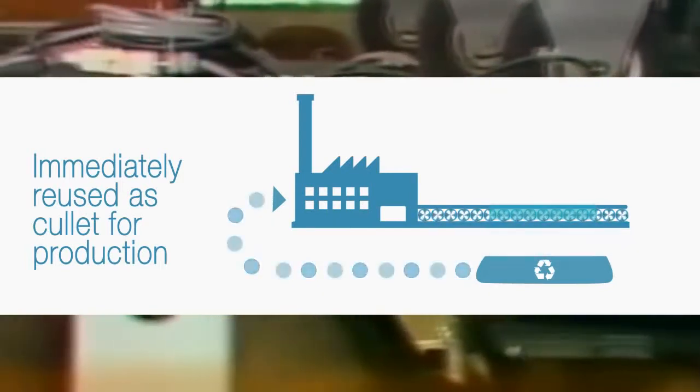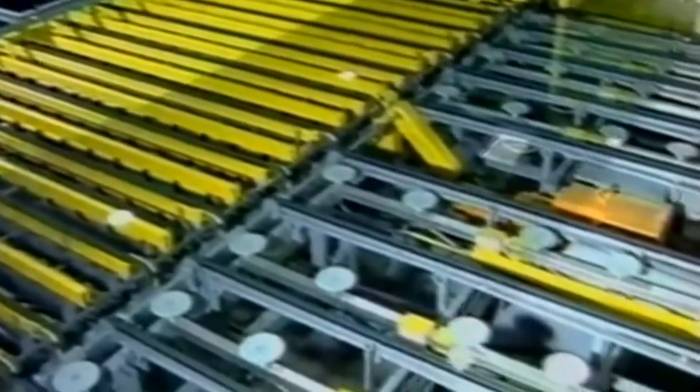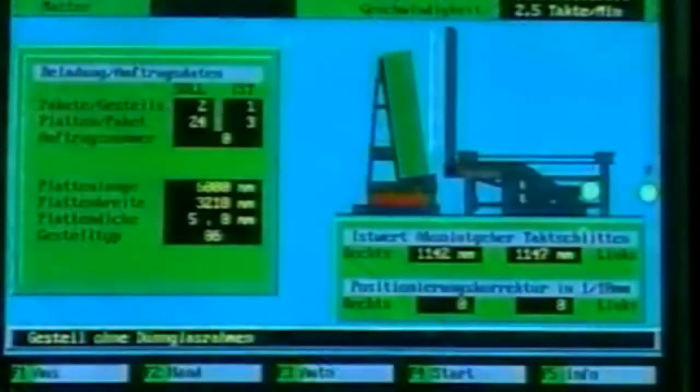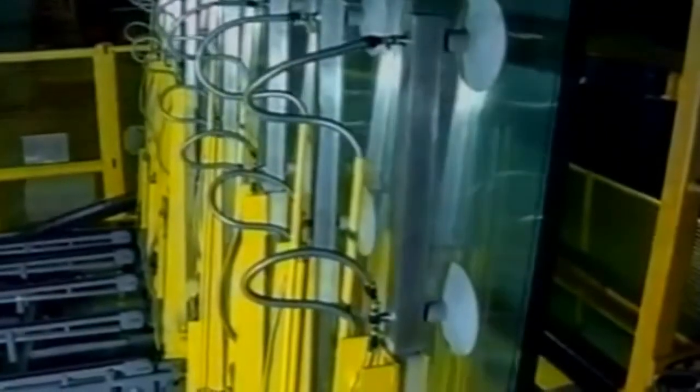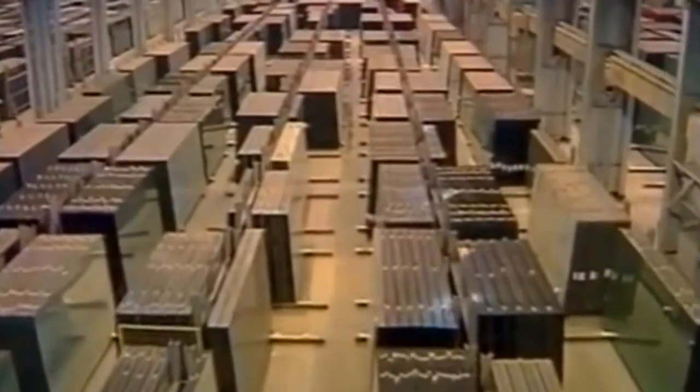The glass ribbon is cut either based on customers' orders or in standard industrial sizes. The most common size in industry is called jumbo. A jumbo piece of glass can weigh between 200 and 500 kilograms depending on the glass thickness. These final glass sheets have perfectly smooth surfaces. They need no further grinding nor polishing. They are ready to be stored thanks to special handling machines.